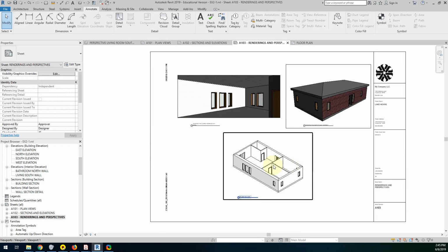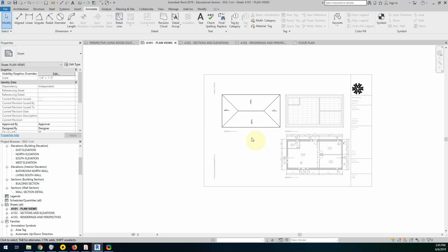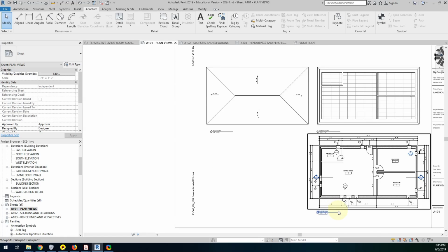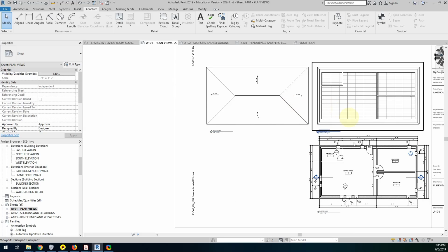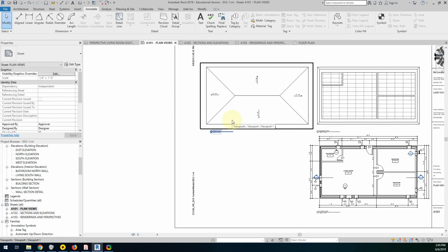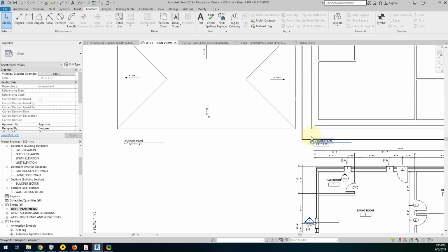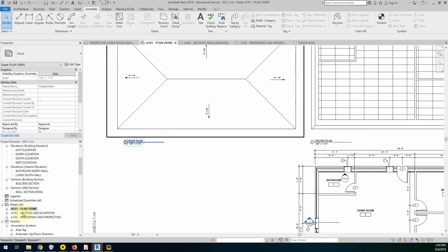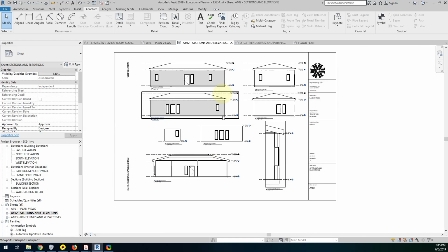And then also address the view numbering. So we should do a Z pattern where we go 1, if there's a view here, it'd be 2, 3, 4, and so forth. So it's going to be in a Z going from the bottom left to right, up to left to right, up, left to right, in that pattern, kind of a Z. These are already correct.